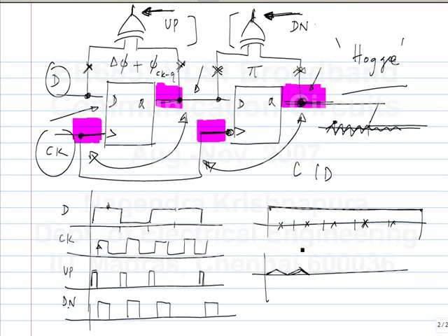If you shift the... yeah. Yeah, possibly. How do you do that? How do you shift the up pulse? Yeah. See, you can do all of that, and one of the things with high-speed circuits is generally simplicity works, right? So now if you have another flip-flop on top of this here and clock it with this, the delays in those flip-flops and so on will not give you the half period shift, it will give you something else. Okay.